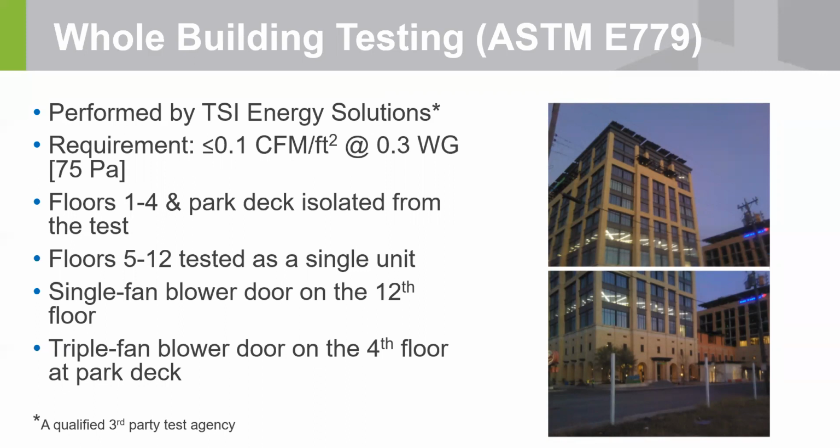They arrayed it with the blower doors as they needed to induce the steady pressure difference. In this case, it was 75 pascals or 0.3 inches of water. You have to maintain that static pressure, and then you can measure the airflow that happens at that pressure.